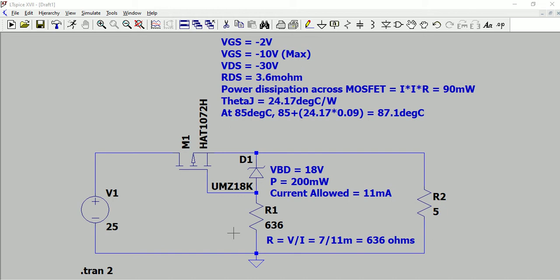So the main difference between using a Schottky method and a P-channel method is that for a Schottky diode, if the load current increases beyond a certain limit, a lot of power will be dissipated across the diode, and you might have to use a lot of copper underneath or use a heatsink to pull out the heat. There is another method, as we said, which is MOSFET based, which can carry higher currents. Power MOSFETs can be used for higher currents and the circuit is designed easily.